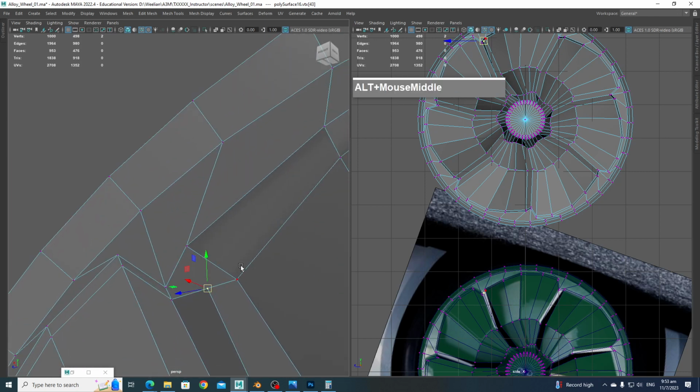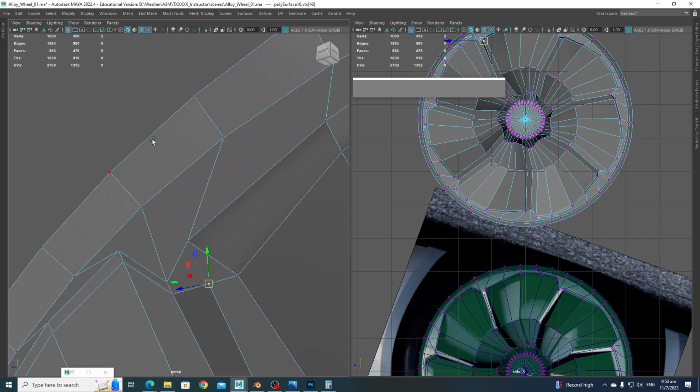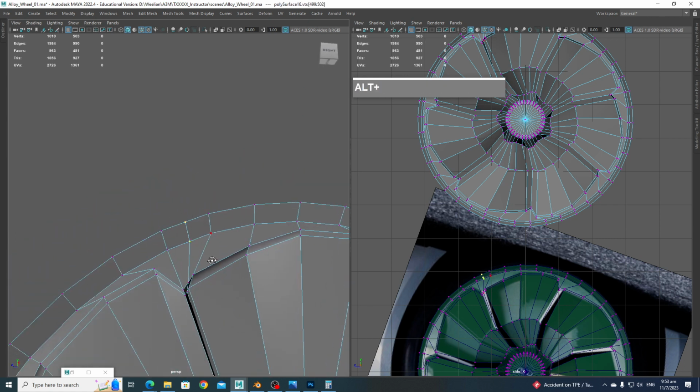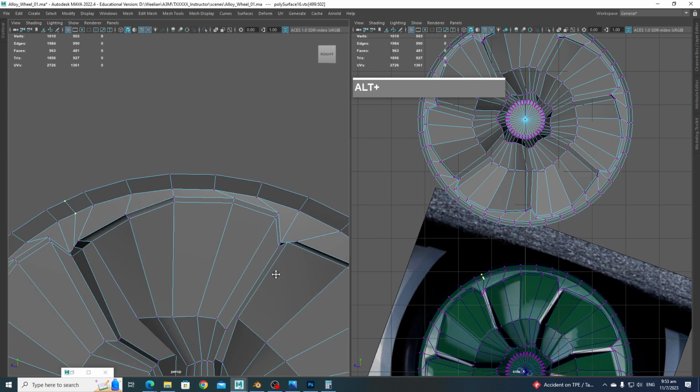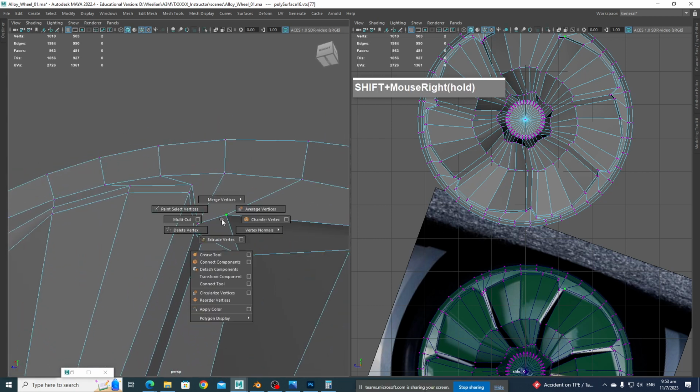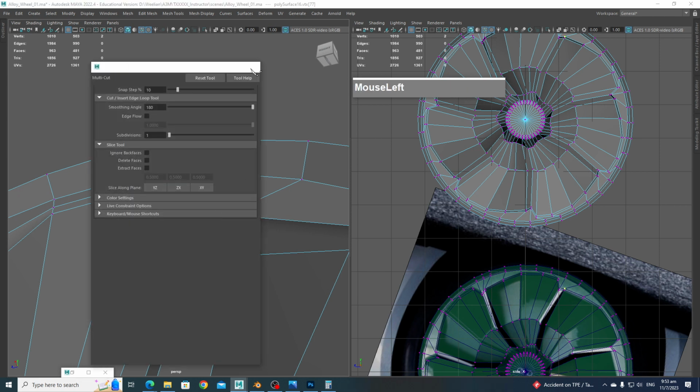Okay, there'll be a multi-sided polygon here, so most likely I will just insert one edge loop that runs across here, like that. Middle mouse click and then connect these components. Yeah. Not exactly the best solution, but I'll work with it for now. Let's do a